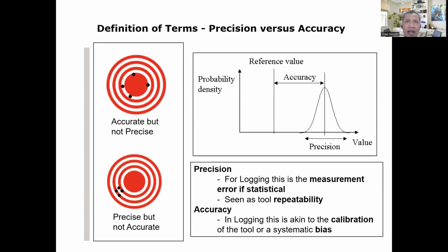Precision and accuracy are two important aspects of measurement. Precision refers to the consistency and repeatability of measurement, while accuracy is how close the measured values are to the expected value. In this context, from the slide, we can see an illustration of precision and accuracy in measurement. Another picture shows an example of measurement with uncertainty, including noise and systematic errors. Another illustration explains the concept of accuracy in measurement.